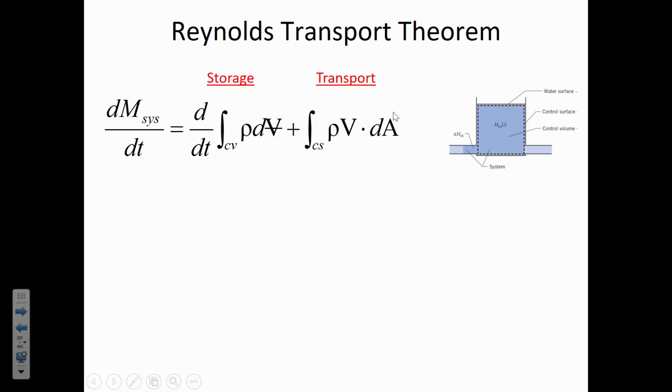Or in some specialized cases, we may have a good equation that defines the velocity profile. And if you have the velocity profile, then you'd actually apply the velocity at some known location to the area that's representative of that location, or we can integrate it if it's continuous. And so V times A, remember, is a volumetric flow rate.